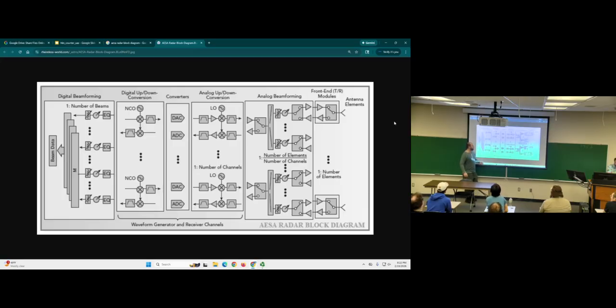But when you do up or down conversion, everyone knows what sample rate is, for the most part. If you want to reconstruct a signal, you need to sample it. That's what's known as the Nyquist rate, also known as 2 times its frequency, whatever that is. Not too complicated. It has to be above that or you risk aliasing and other issues. Well, the problem you're going to run into is these radars are not operating at 200 megahertz. They're not operating at a gigahertz.